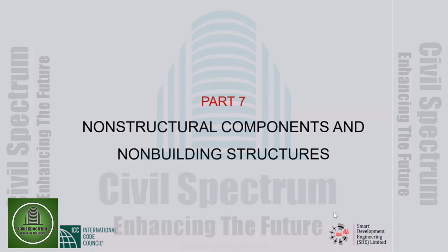All steel structure questions, which I have not really covered. Is it always adequate to take 30% earthquake load on orthogonal direction in horizontal earthquake load distribution? I'm not sure what the question is. If you are questioning whether 30% is adequate or we should go to something like 40%, 30 is what is required. If your judgment tells you you should take more, you are free to, but I have never seen anybody do that.